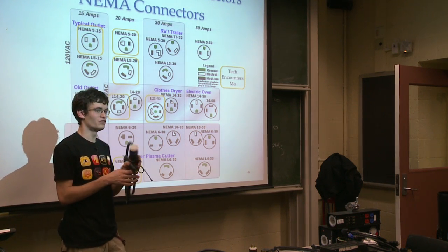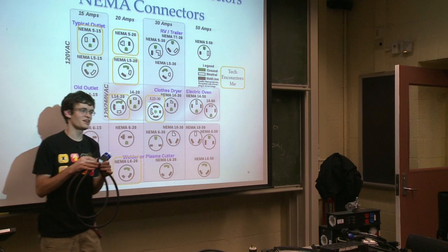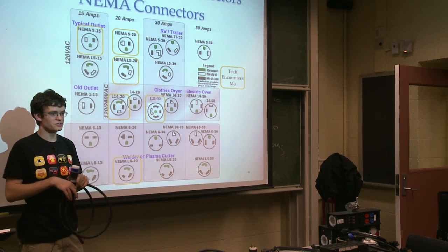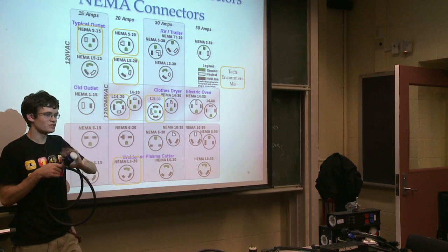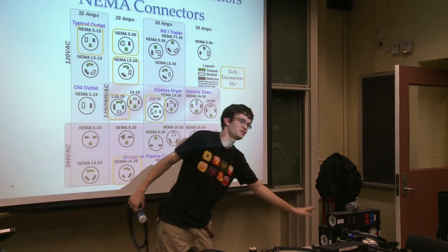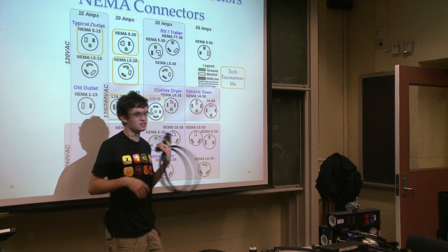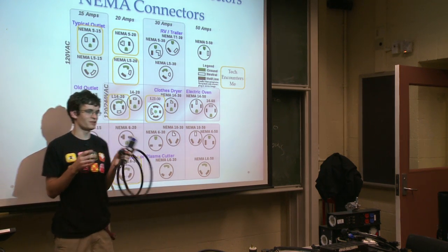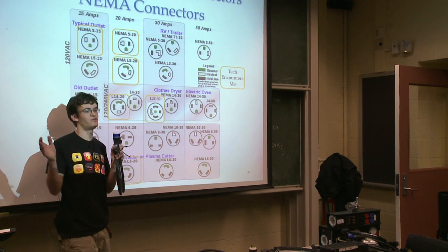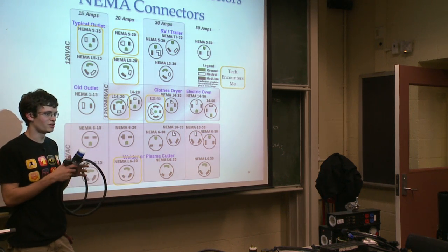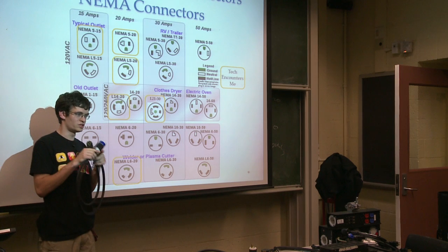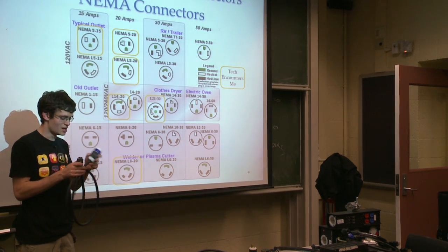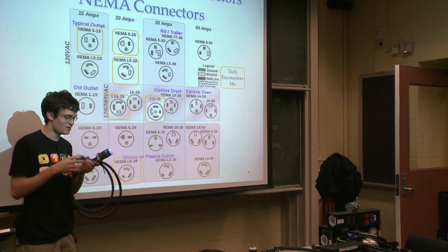We made it for our moving lights, which have switch mode power supplies that could accept anything from 90 volts to I think about 260 volts. So we put L620 connectors on them so we can easily plug them into the L6 breakouts and run them on 208 volt. However, in the case we need to run them on 120 volt, we made these cheaters. They don't care which plug is on them as long as they get somewhere in that voltage range and sufficient current. So with this plug, you can give them 120 volt. They'll use more current, but it's well within their safe operating capacity and standards, and they'll be fine.